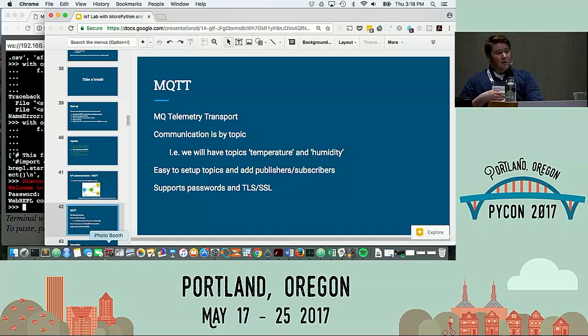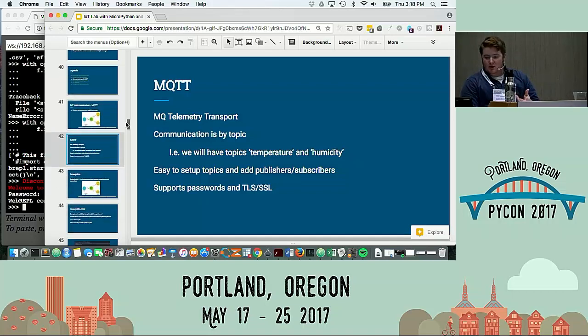And then on the subscriber side, say in wineries, they have heaters throughout the vineyard in case it gets very cold and they don't want the vines to freeze. Maybe those heaters would subscribe to a temperature topic that would let them know, hey, the temperature has been at this low point for a while, it's time to turn on the heaters. In that way, you can decide what parts of your network receive specific messages. That's the idea of how topics are used within MQTT.